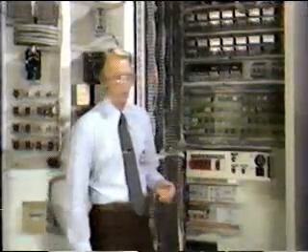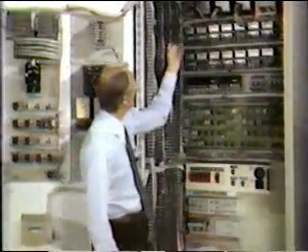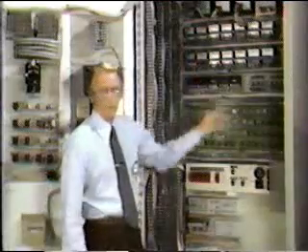Let's take a closer look at how the servo actuator is controlled. Now, first we know the signals are sent from the ramp generator and main fuel actuator control, as well as the governor, to the servo actuator. And second, we know that the temperature monitor, speed monitor, and governor control determine which device will control the servo actuator. As the engine begins to rotate, the magnetic pickup G383 sends a signal to the speed monitor.